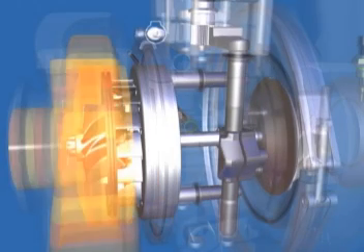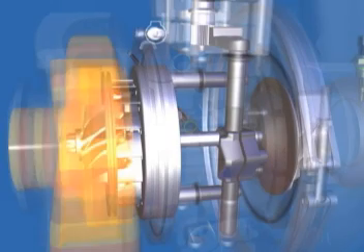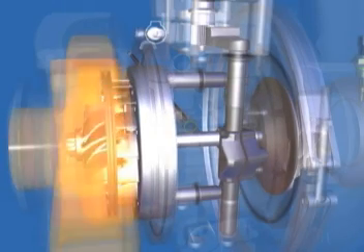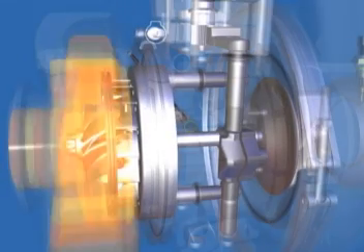With the nozzle ring in the fully open position, the turbine volute exit area is at its maximum. This creates the minimum exhaust manifold pressure. Turbocharger shaft speed and boost are at their lowest. The sliding nozzle position is infinitely variable between open and closed.